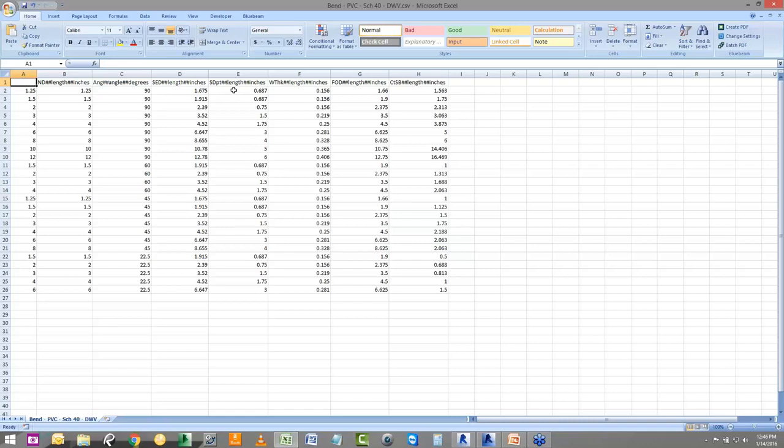So now I know that this value is what drives the socket depth. Note that I placed that 6-inch fitting. Here's the 6-inch size in the lookup table. We have a 3-inch socket depth, and if I go all the way over to the right, center to the socket bottom, which is the length, I'm going to see that that is a 5.